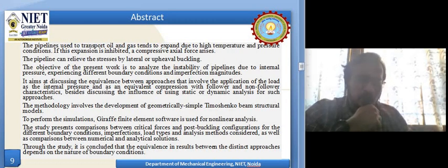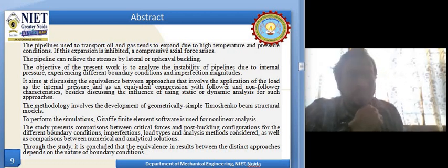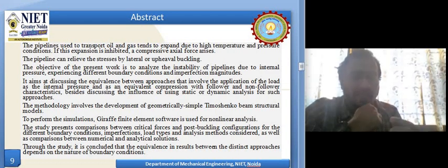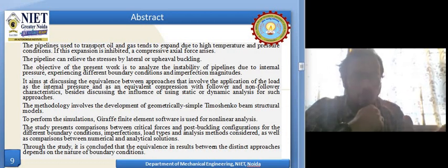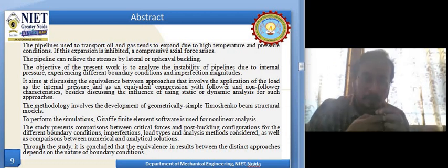So in this particular project I'm going to make a new support that allows six degrees of freedom. As we know, six degrees of freedom is nothing but the motion, or you can say displacement, in x, y and z directions along with the rotation of the pipeline about its center line. So it may be dx, dy, dz, or you can say mx, my and mz. So a kind of flexible support will be provided.